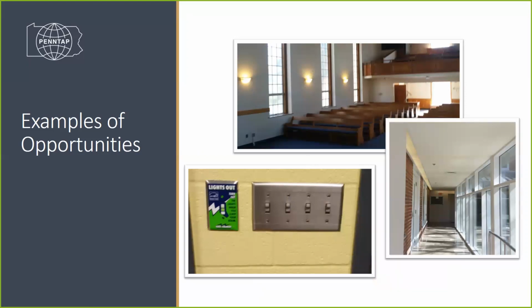When looking for lighting, look for opportunities where lights are on during a time when maybe you could be using natural daylight. Or look for lights on in areas where there is no one. Walk around and try to identify areas that make sense where you can replace with newer technology. There are many areas to investigate during a walkthrough phase. Look at your lighting, your building envelope, the parts of the HVAC system, as we talked about, hot water systems, your air distribution, and your office equipment.